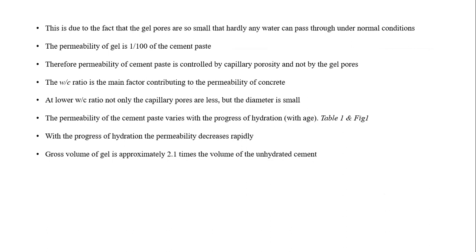This is due to the fact that gel pores are so small that hardly any water can pass through under normal conditions. Therefore, permeability of cement paste is controlled by capillary porosity, not by gel pores. Thus, the water-cement ratio is the main factor contributing to the permeability of concrete, and with a lower water-cement ratio, not only are the capillary pores fewer, but their diameter is also smaller. The permeability of the cement paste is explained in the next figure.